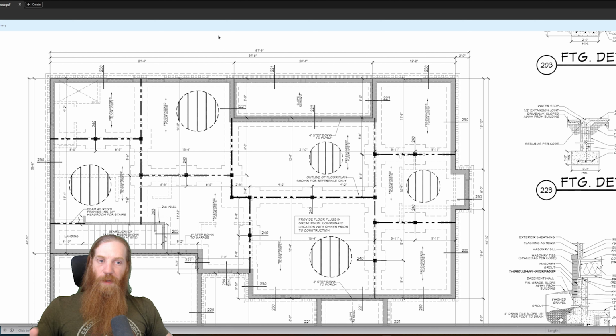So we know that this building, including the bump out here, because you can see that the 61'6" comes all the way out here and lines up with the exterior edge of the wall for that bump out. Now I already said we're not really gonna do the bump out. What I'm gonna do is bring this wall and this wall out to all be just one wall at the same distance out as that bump out. So we are still going to be going the 61.5 feet, and then it's just going to be a straight wall all the way down and then come back across the bottom.